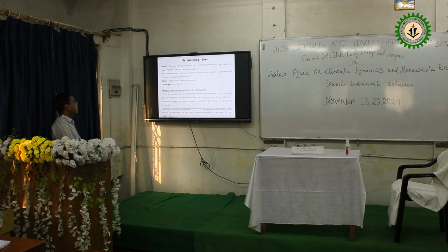This happened through technological innovations and the net metering camp. It happened recently in 2021, when renewable energy sources were implemented in bulk, as well as the integration of grid connected solar PVs and other renewables. So if we talk about West Bengal, Odisha, Tripura and Chhattisgarh, consumers having different sanction loads and contract demand up to 5 kilowatt may set up a solar PV system under the net metering arrangement.